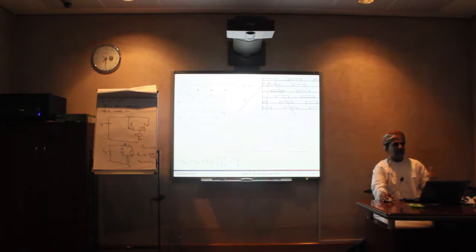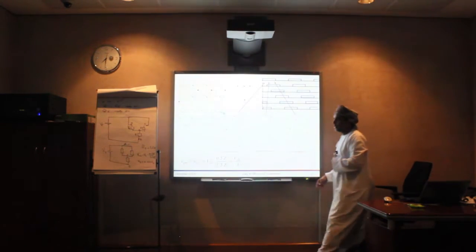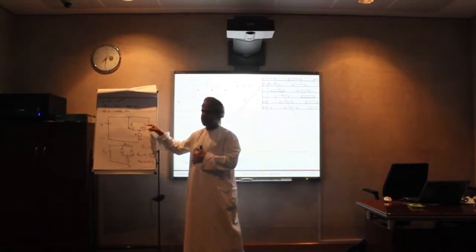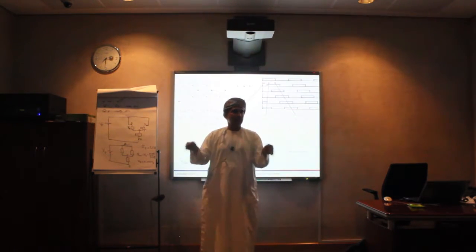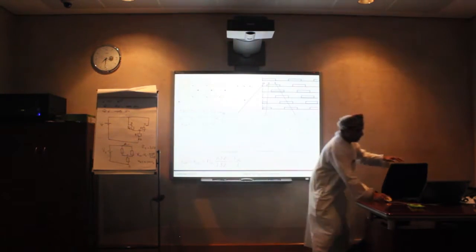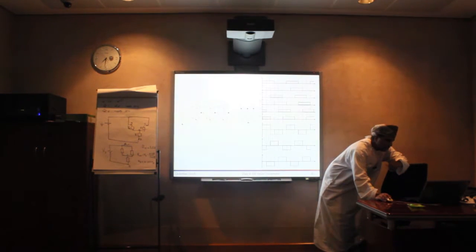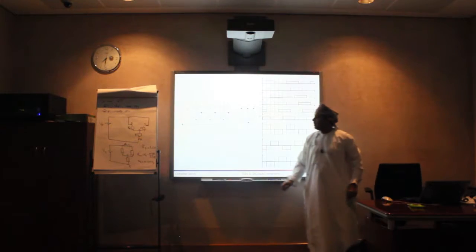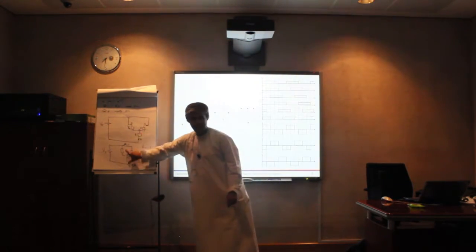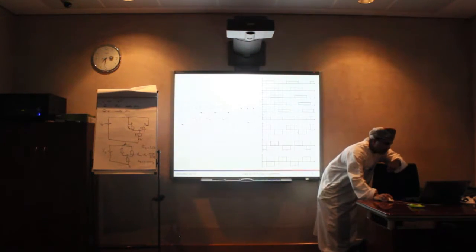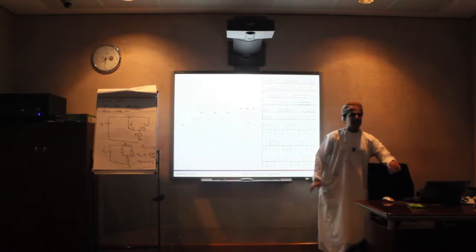So now we can get VAN, VBN, VCN. Also we have line-to-line voltages, right? So we can get, for example, VAB, VBC, and so on. We can apply those circuits. For example, if I ask you on this first interval, what is the value of VAC? It's the same node, so the value of the voltage is 0. So VAC is 0, VCA is 0, right? And if I ask you what is VAB, from A to B? VS, exactly. So VAB during that is VS, and so on.